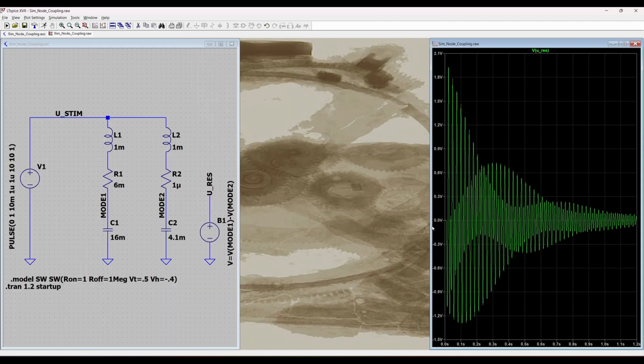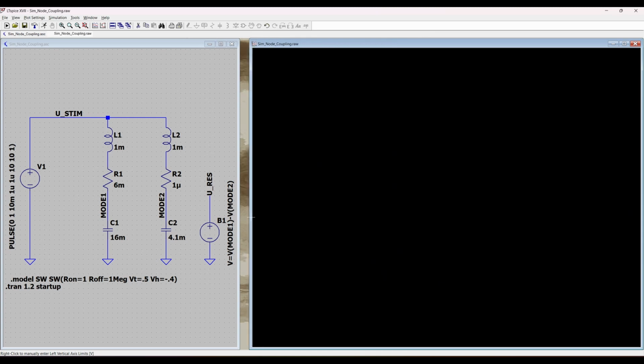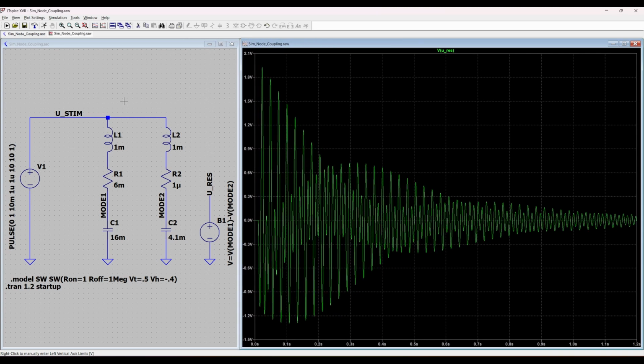We can actually use LTspice to replicate this waveform. Here I have two resonance circuits. One is resonating at 39 Hz, representing the first eigenmode, and the other is resonating at 78 Hz for the second eigenmode. I've just added the waveforms together using a programmable voltage source, and the resulting waveform resembles what we can see on the scope. Okay, the first simulation was a success.